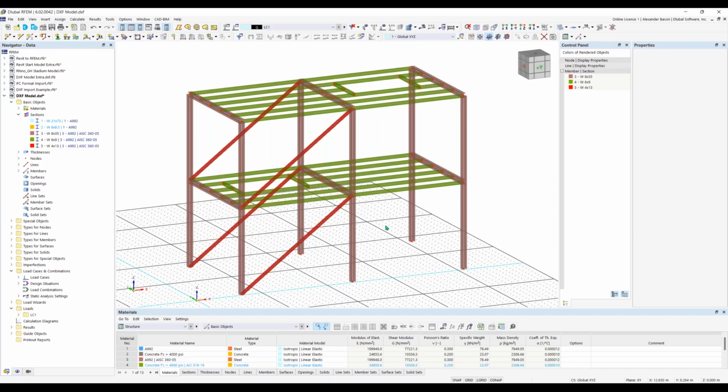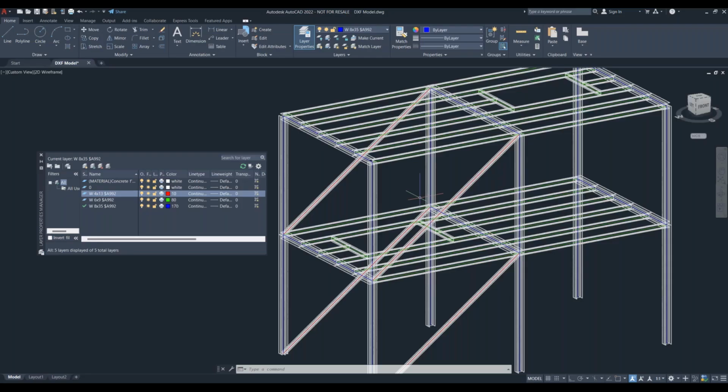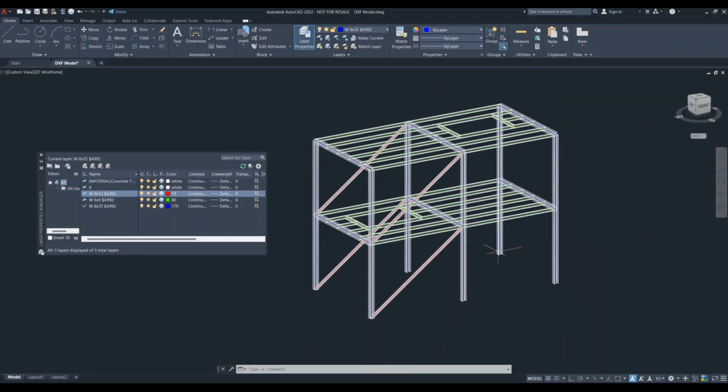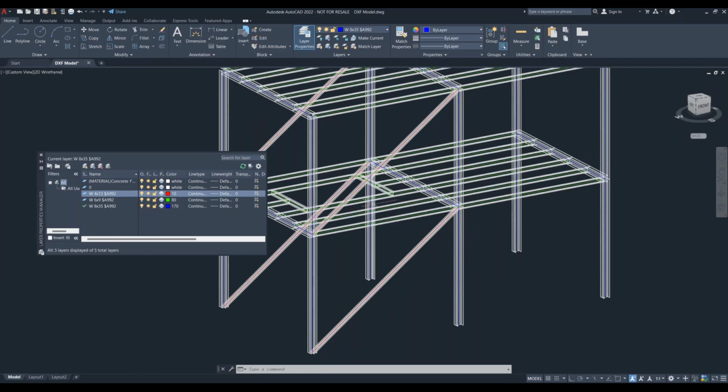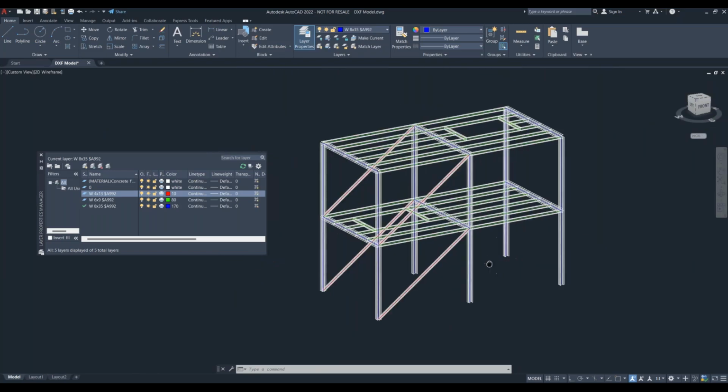And this isn't suitable for everyone. Since you have to create the analytical lines in AutoCAD, if you haven't already done that, it might be a lot of work, and maybe you're better off modeling them in RFEM. But it might be helpful for companies that use blocks in AutoCAD, maybe use very similar structures, and maybe the same type of structure all of the time. And if in your blocks you already have the analytical lines modeled, then this could be a really easy solution for you.